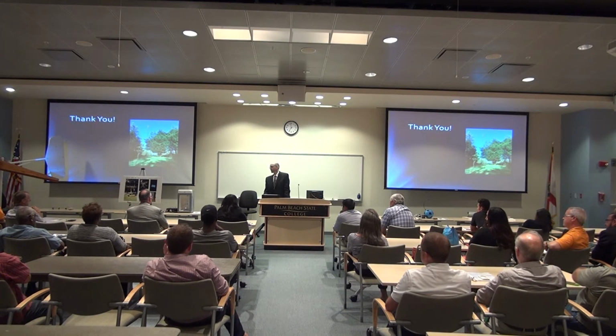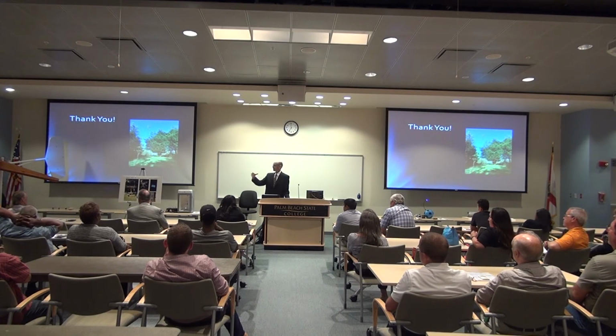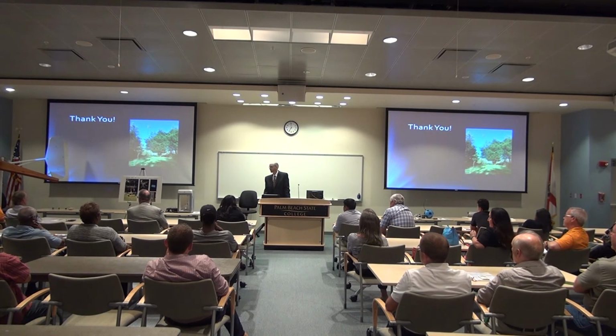This turbine would require sort of hands-on monitoring if you expected a very powerful storm to come through and very high winds. So, I wouldn't just rely on the furling to protect it with 100-mile-an-hour winds, but for day-to-day usage, it should furl. The hub is actually offset from the yaw axis, so the tail will stay facing into the wind and the hub will actually hinge in on itself and reduce the area exposed to the wind.